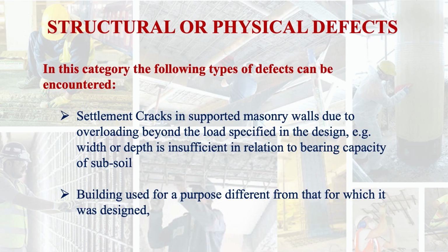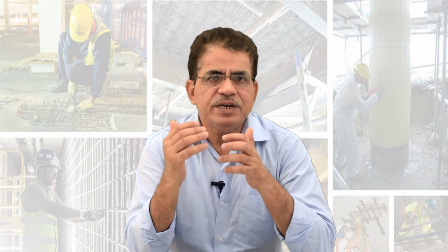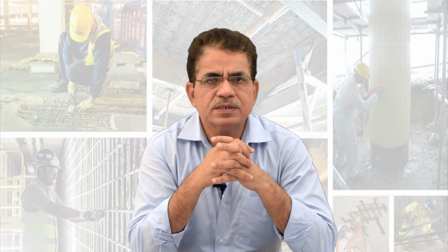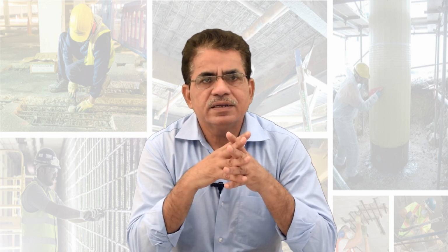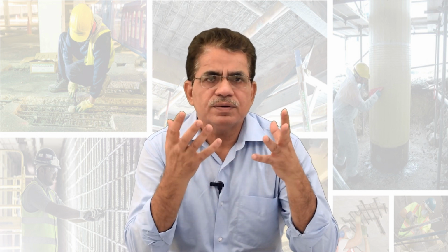Building used for a purpose different from that for which it was designed. Here the loads taken for the design will be different now. For example, the design was for residential purpose, but later on you are using it as a warehouse, so certainly the loads are going to increase. Such a building will certainly experience some problems, some damages.